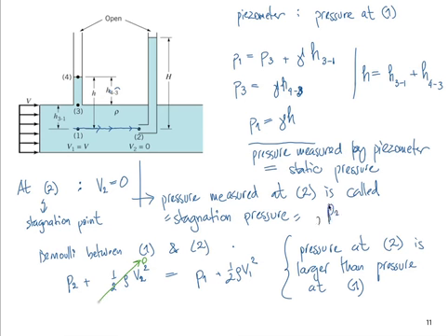Stagnation pressure happens in the fluid whenever the fluid comes to a complete stop. And it happens in any situation of a submerged body, for example, flow around an airfoil, flow around any object. There will always be a point where the fluid comes to a complete stop, and that's a streamline. That is the stagnation streamline, and that allows us to measure this stagnation pressure. So we'll continue from this point on next class.